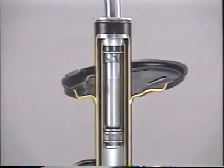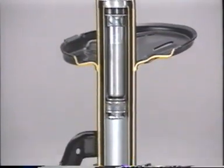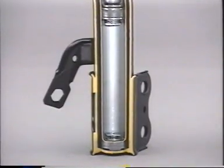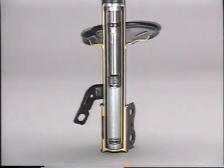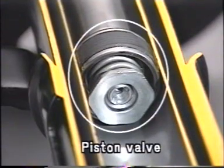The twin tube type is a double layered tube with a piston that moves up and down in the inner cylinder. The piston is fitted with a piston valve, which generates damping force when the shock absorber is extended.